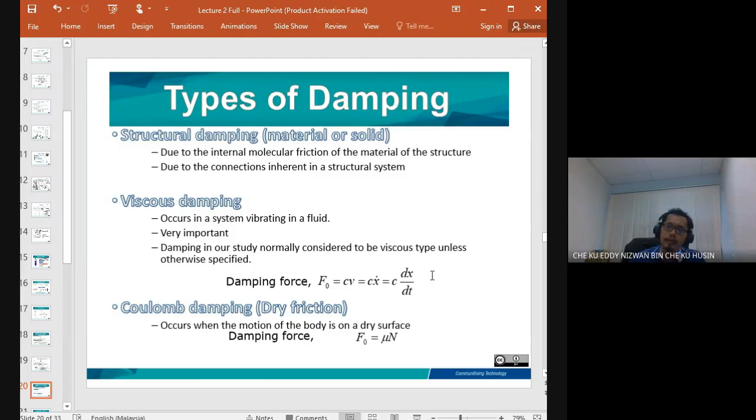So it's related to the critical damping value. For example, if you require 2000 Newton seconds per meter, then you have to design the damper. Your absorber should have a damping coefficient equivalent to 2000 or more.